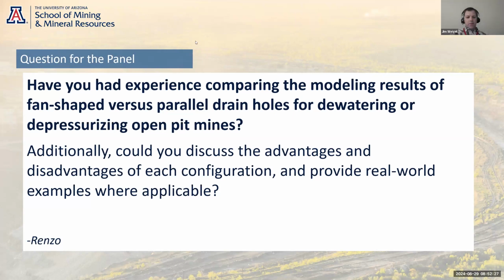Yeah, just the comments Jeremy just made around looking at the structures. One component of that too is there can be a lot of cost savings on that. We ended up doing that in our underground drainage gallery and reduced the number of drains quite substantially, but oriented the drains more favorably, and as a result ended up with better depressurization for less money.